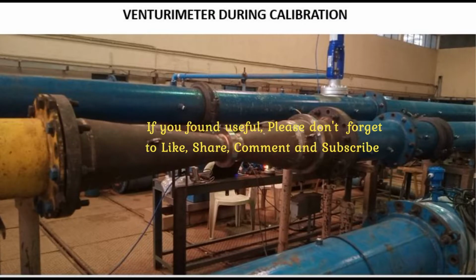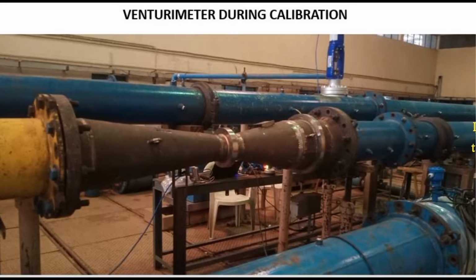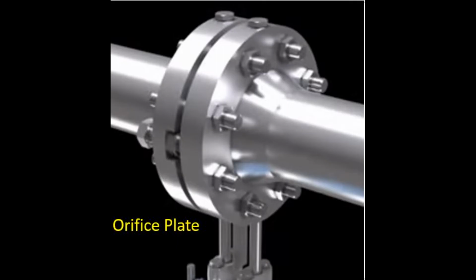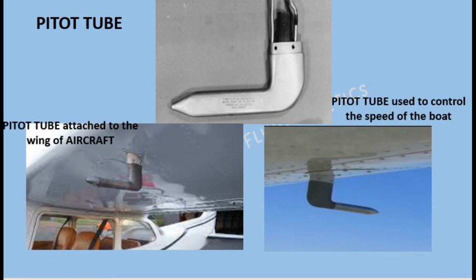Today we are continuing the discussion on the application of Bernoulli's equation for the measurement of discharge. We have learned previously about different flow measuring devices like venturimeter, orifice meter, etc. So these flowmeters are developed based on the principle of continuity equation and Bernoulli's equation. These flowmeters are also called differential flowmeters because for the computation of discharge, the only measurement we have to conduct in the field is the measurement of differential pressure head. The device which I am going to introduce today is the Pitot tube.